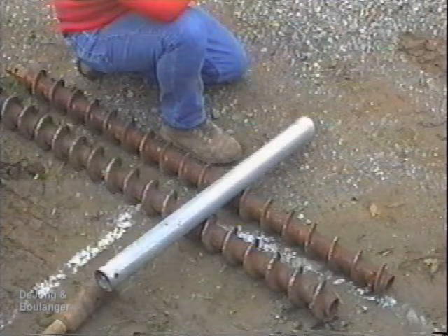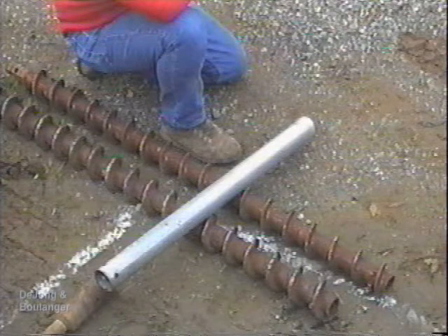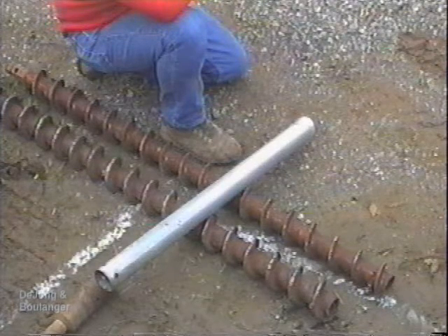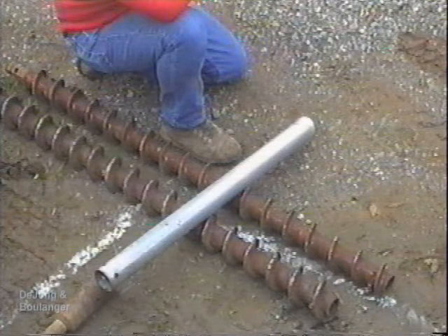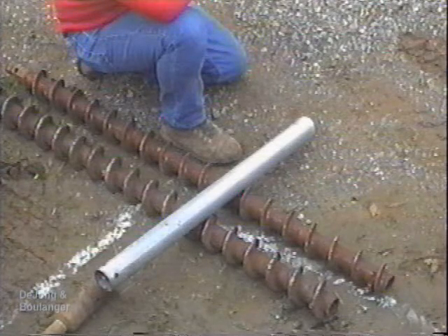Piston samplers with small area ratios are capable of furnishing excellent samples of cohesive soils, even if very soft and sensitive. The necessity for a separate piston rod rising through the drill rods to the ground surface can be eliminated by using a hydraulically operated mechanism such as the Osterberg piston sampler.